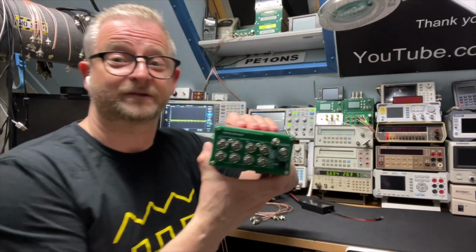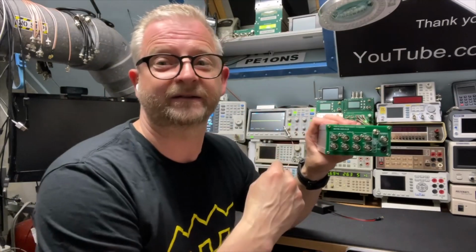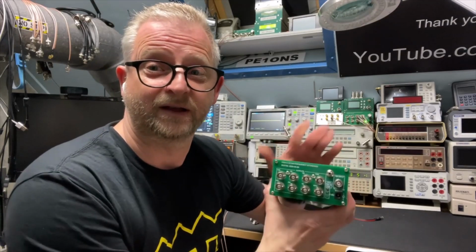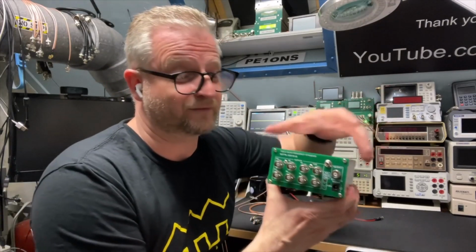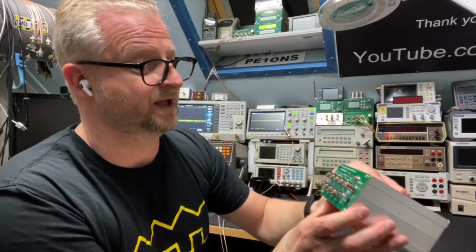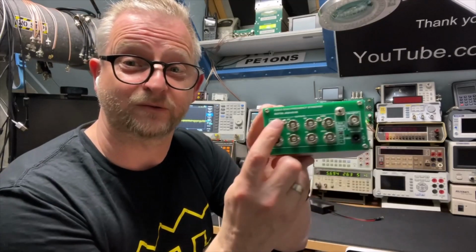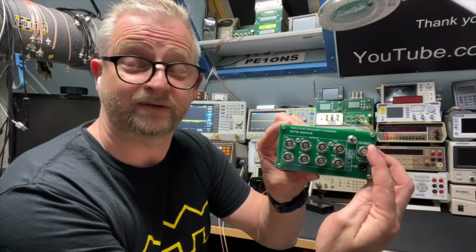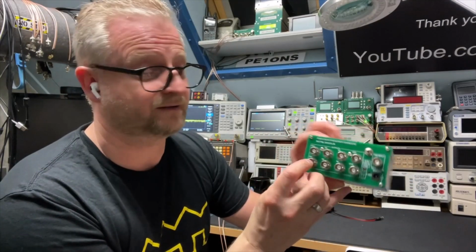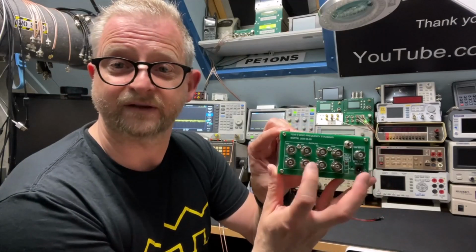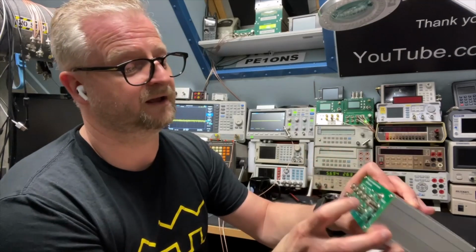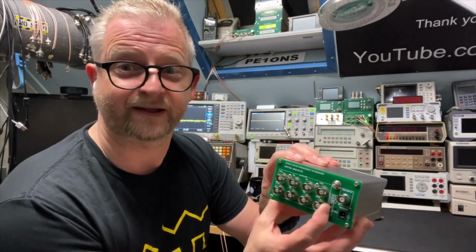This is also with an internal oscillator, but like the 10 megahertz distributor, when you input the 10 megahertz here, it will switch off. I made this switch so I can switch it off because I never used the internal oscillator. But what does it do? It has two outputs. So when you input 10 megahertz, it outputs 10 megahertz, 10 megahertz. It also outputs 5 and 5 megahertz, and also 1 megahertz and 1 megahertz, 100K and 1 pulse per second.